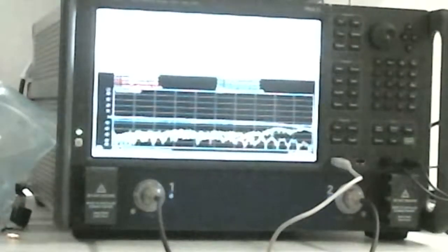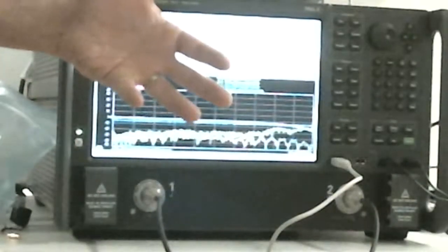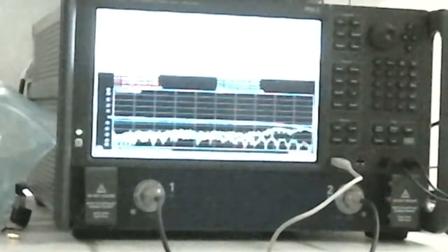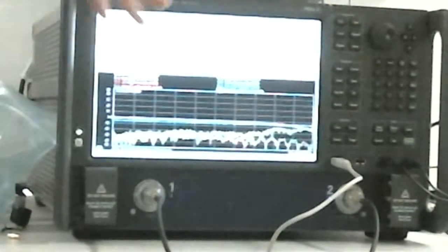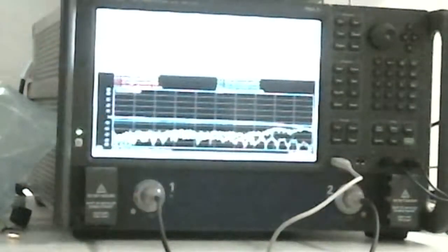So the speed of light is 3 times 10 to the 8 meters per second. If this is about a 30 centimeter cable? You can look up what it says. 18 or 24 inch. Okay, so it's a 2-foot cable. You can look at the 24 inches and figure out what that means in terms of length, and you should find that this is fairly good. Of course, because this is a Teflon cable, you have to use the square root of the dielectric constant. Again, this just gives you a rough estimate.